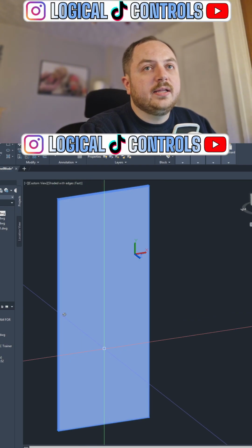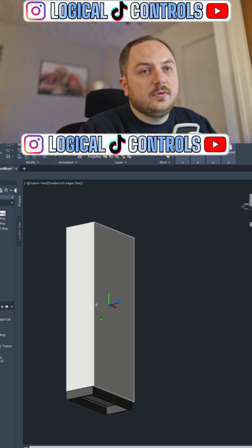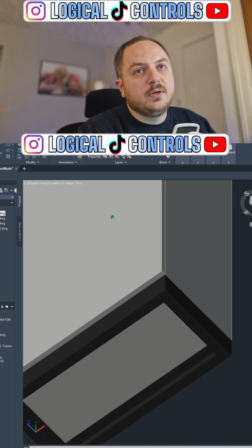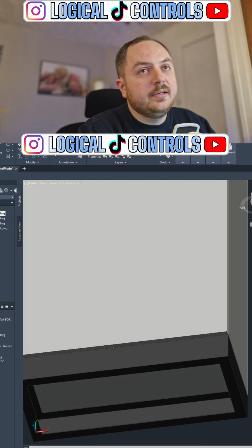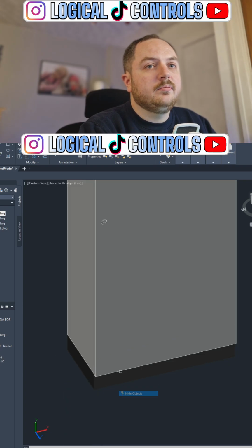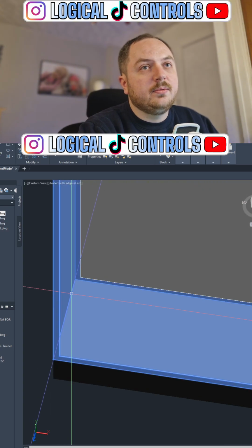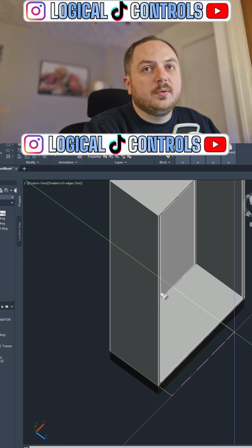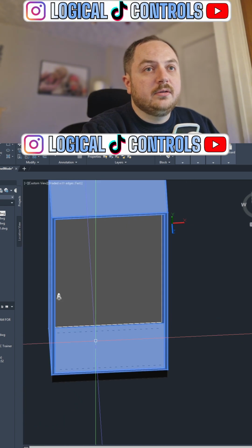Yeah. So, okay, there's our door. Let's bring everything back. There's the full enclosure itself with the plinth. It's a basic plinth, and we'd probably actually as well, while we're on with it, do a cutout in the bottom of the enclosure and put an aluminium gland plate in. If you have a load of cables that take any sort of current, I mean, if it's less than 100 amp, you probably don't even have to bother. But I tend to, as a matter of course anyway, put an aluminium gland plate in. If it's less than 100 amps, you probably get away with a steel one. It's not a problem. But you're trying to limit the eddy currents between the cables coming into your enclosure.